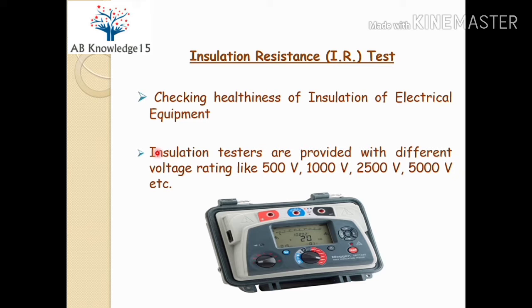First of all, why are we carrying out this test? The purpose of this test is to check the healthiness of the insulation of an electrical equipment. Whatever the electrical equipment, there must be insulation, and the insulation is capable of sustaining up to its design voltage. So we are checking the healthiness of insulation by carrying out this insulation resistance test.